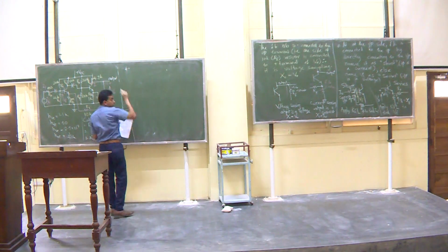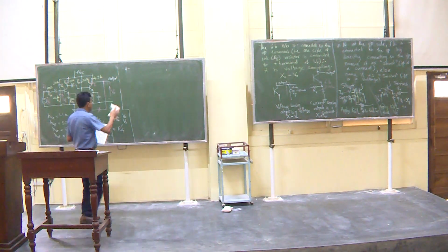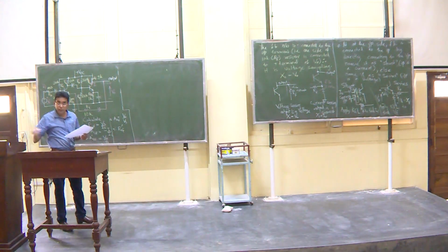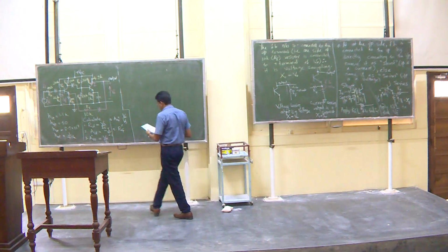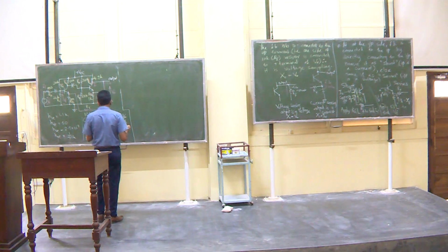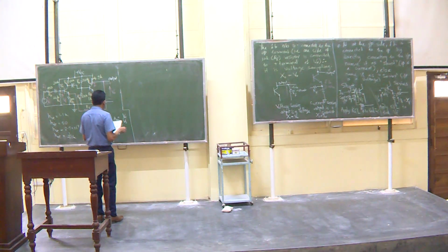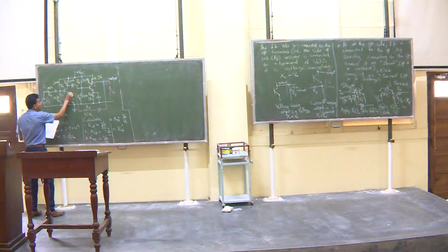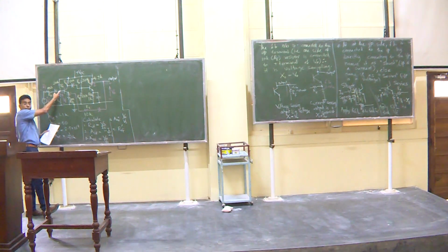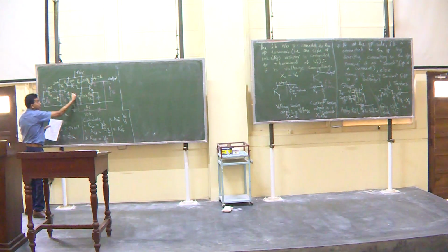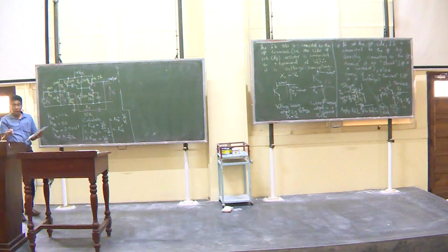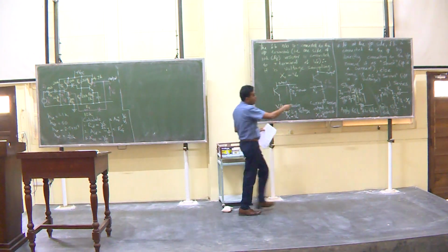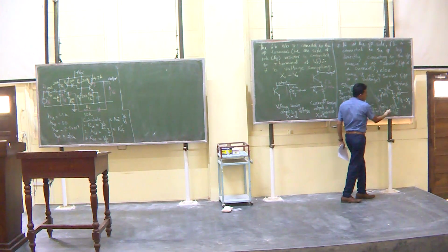The fourth step, so let us figure out for our circuit, for our example what this is, right. In our case this is where we connect it. Is it the input? Are we connecting the feedback component directly to the input or somewhere else? Somewhere else. If it is somewhere else, we have to apply KVL to find that.